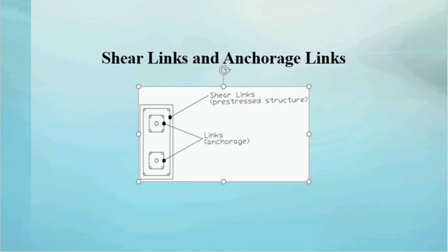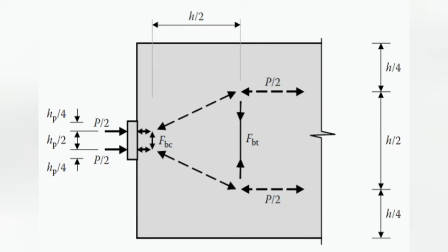The amount of reinforcement link also needs to be decided by the appointed engineers. We just provide some area of reinforcement for the case study only. The force from the post tension cables is also just assumed, because in a real life project, the procedure to determine the force from the cable is quite tedious.